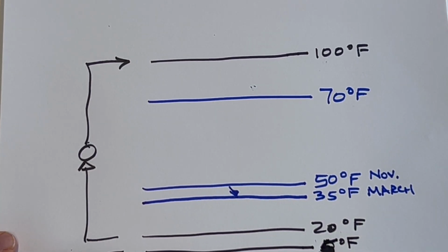Later in the winter, as we head towards spring, for the same outdoor air temperature, we will be using more power with a ground source heat pump as the ground temperature and the return water temperature from the ground to the heat pump goes down.